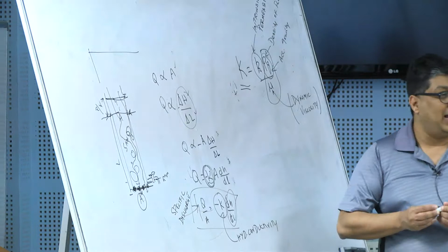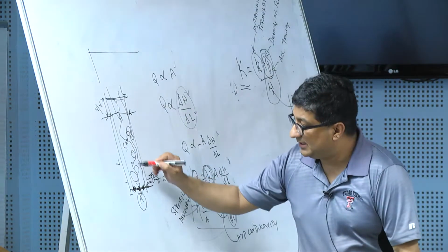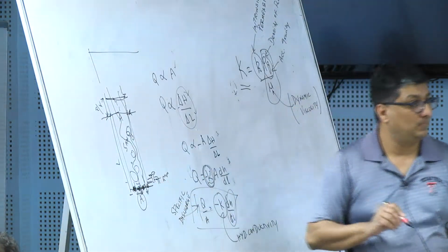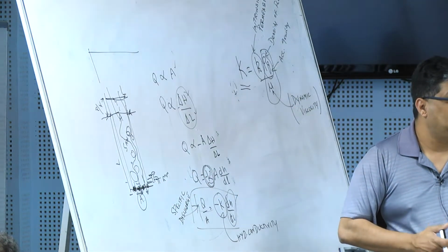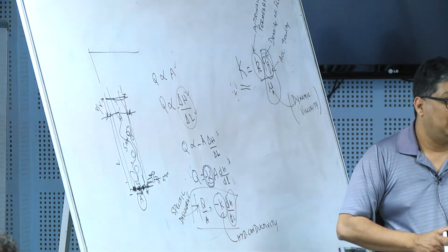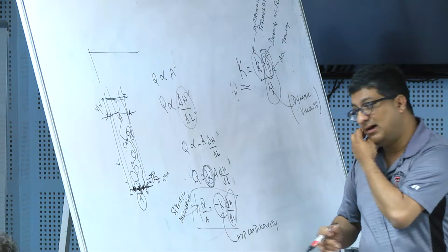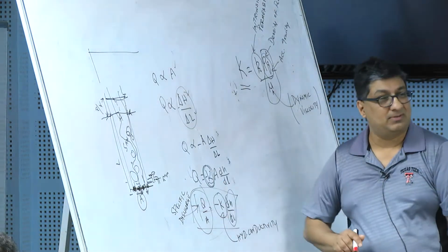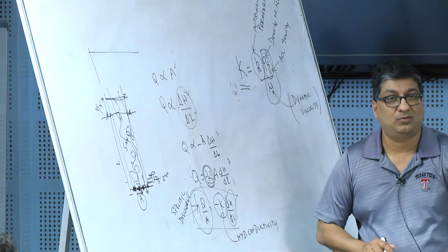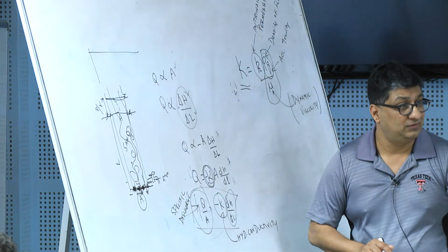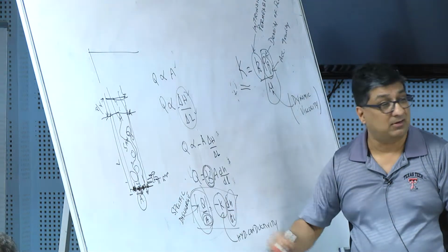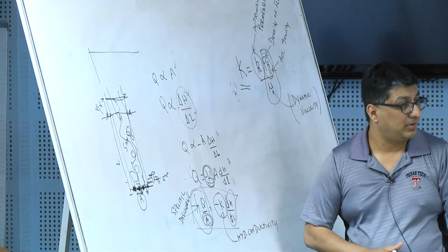In reality, the water is only moving through the pores. So the velocity with which the water moves is different from the flux or the specific discharge I'm calculating, because the water is only moving through pore space, whereas the flux is being calculated over the entire cross-sectional area.